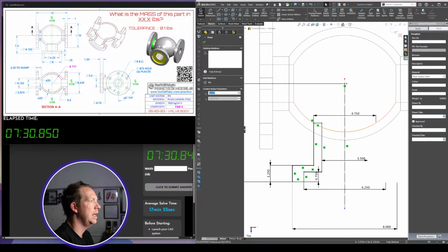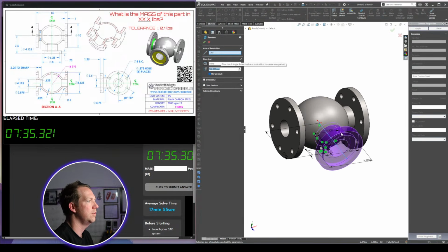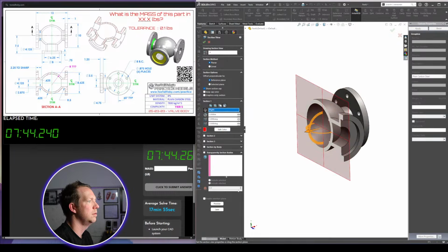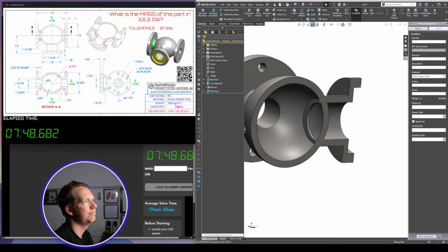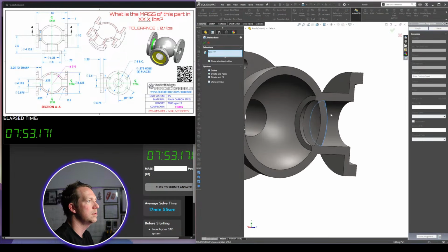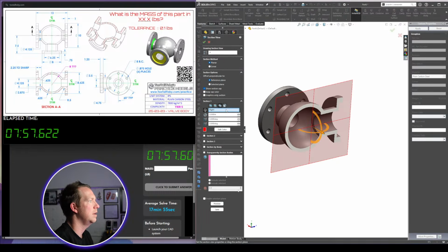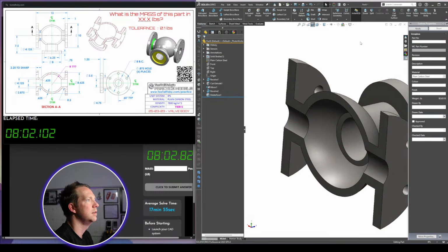Just going to bring that to that edge, that way it's fully defined. Then I'm going to revolve this. I'm going to merge, and the way to get rid of this element in the middle and that element on the inside, it's not the nicest, but I wonder if we can just do a delete face to get it done.